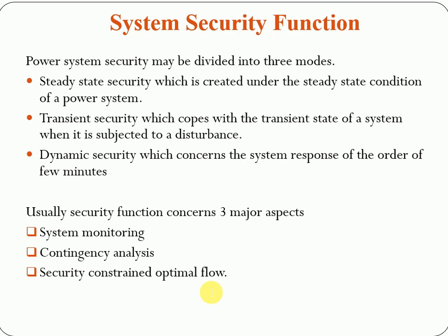The SCADA system makes real-time monitoring and correction of overload or out of limit voltage available. Commonly, a SCADA system is composed of three types of communication equipment: human machine interface, HMI, master terminal unit, MTU, and the remote terminal unit, RTU. SCADA is a high-tech computer supervision and control of the power system network.